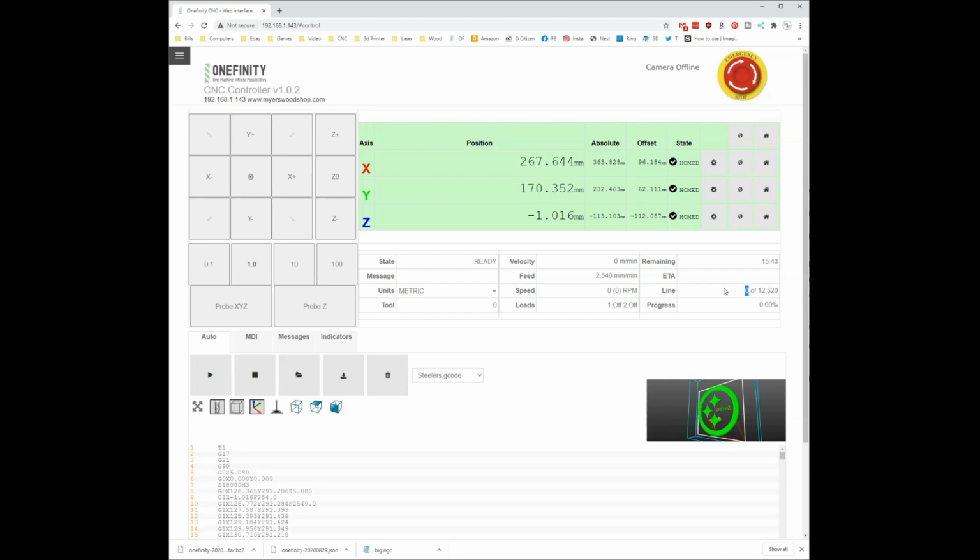On the Makita, what speed do you run it at? I'm generally around a 3.5, 4 is okay. I'd say that's the majority of what I'm cutting at. On the DeWalt, I was at 3, and this one has a greater range, so it was like 3.5, 4. Okay, thank you. Usually most things online that give you G-code simulators and stuff, they're calculating the spindle to be around 18,000 RPM. So that's what I usually keep it at.